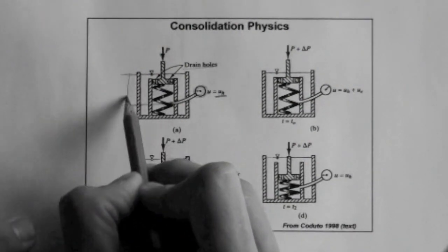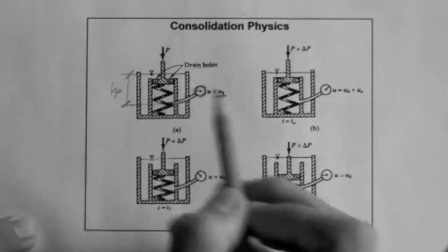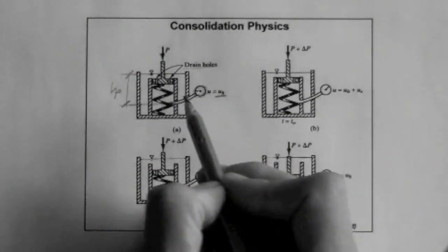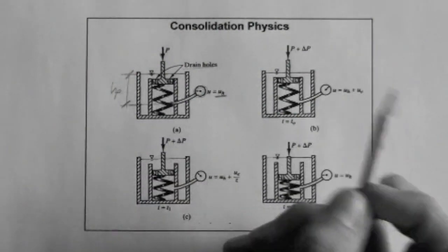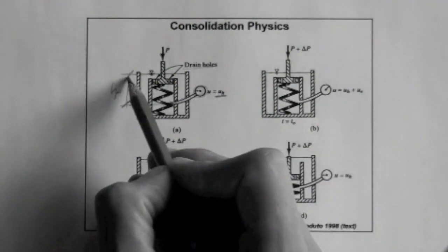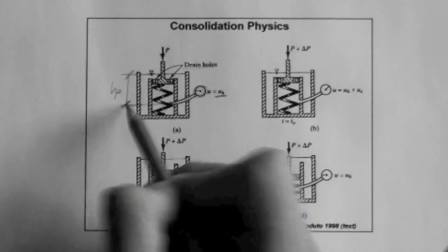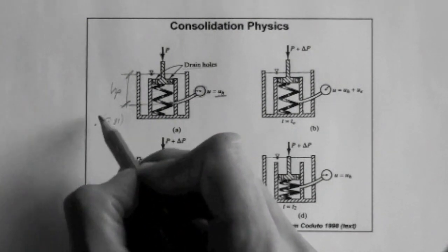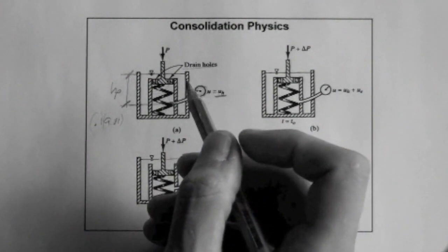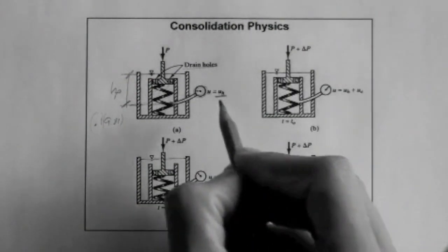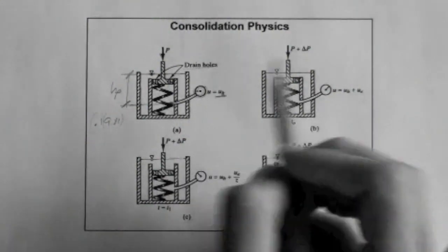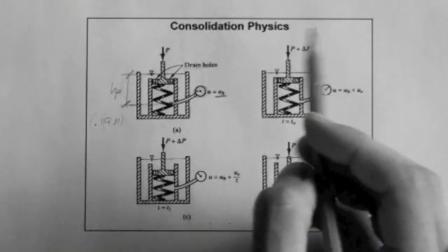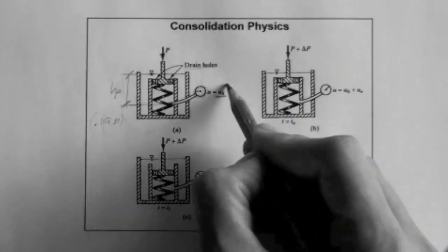Well, you would say, here's the point. What's the pressure head? The pressure head is this. The hydrostatic pressure head, well, in this case you would say, yes, because it's the distance from this point to this water table. And you would say, okay, that is 0.1 meters. 0.1 meters times 9.81 kilonewtons per cubic meter is 1 kPa or so. So then you come here and you read, oh, 1 kPa, okay. That means that this system is in hydrostatic conditions. The water is pressurized only because of its self-weight. Fine. So you check that that is the case.